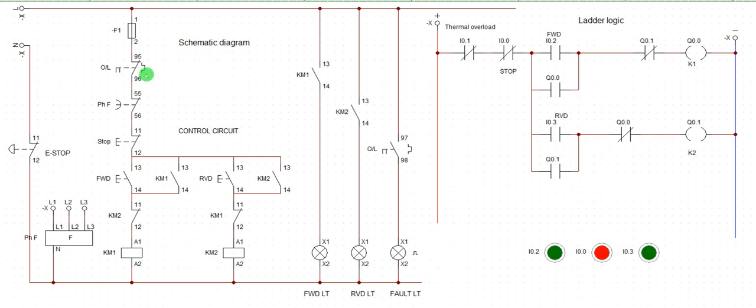Okay. Now, this is my thermal overload, and this is my thermal overload. This is the symbol. Then this is phase failure, I don't need it. This is the stop button, and this is my stop button. Now this is the forward operation start button, which is this. Now this is my electrical interlock, and here is the electrical interlock. That is K1. Okay, this is K1.